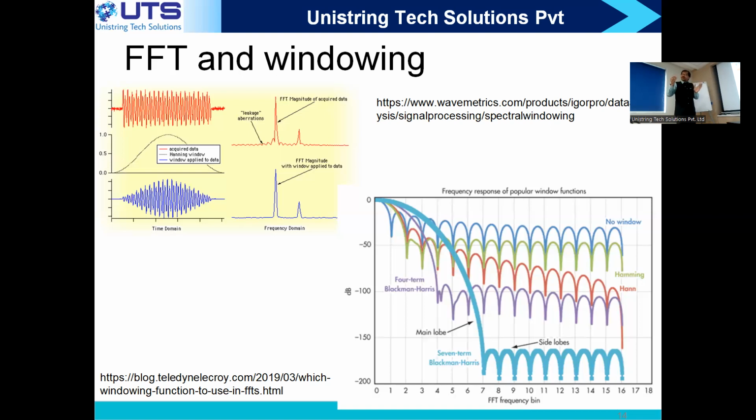Even though you give a simple sine wave, technically it is supposed to come in only one bin. But it won't be restricted to one bin because you took only 256 microseconds. If you want a very high precision frequency, you need more time. So even for one K value where you are supposed to see the peak, it actually distributes into the other bins. I think the next lab exercise is going to have a couple of experiments on this, the FFT, spectral leakage and all. Are you following?